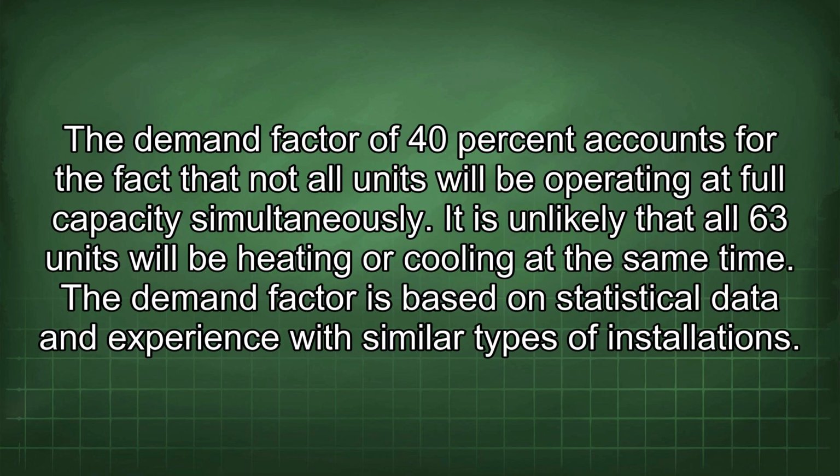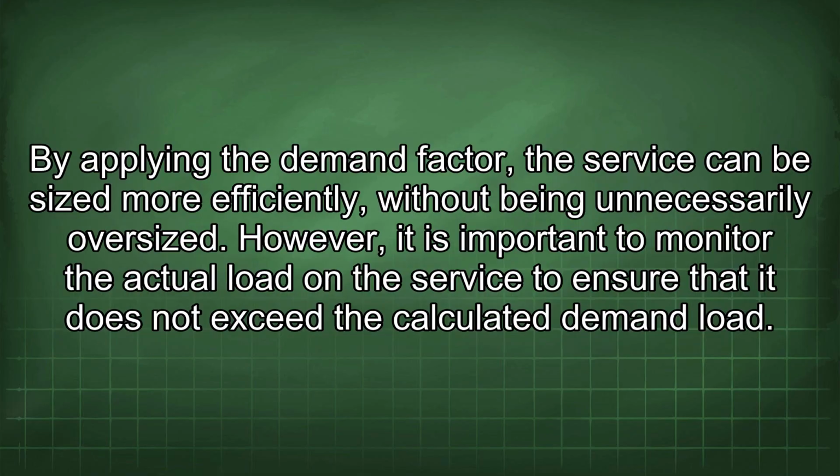The demand factor of 40% accounts for the fact that not all units will be operating at full capacity simultaneously. It is unlikely that all 63 units will be heating or cooling at the same time. The demand factor is based on statistical data and experience with similar types of installations. By applying the demand factor, the service can be sized more efficiently without being unnecessarily oversized.